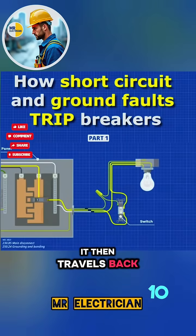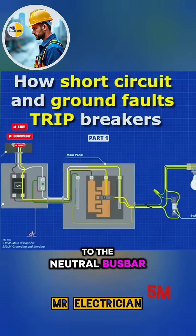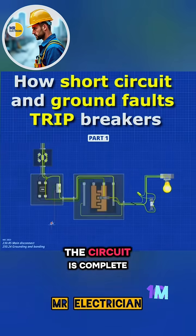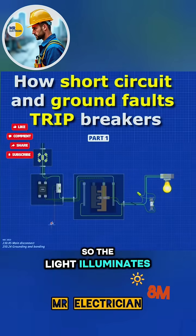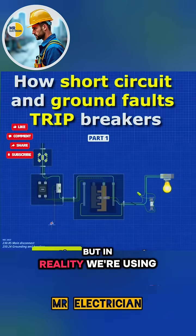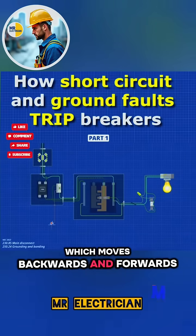It then travels back along the neutral wire to the neutral bus bar, and then back to the main disconnect, then back through the meter and over to the transformer. The circuit is complete, so the light illuminates. Now, I have animated this using DC current as it's easier to visualize, but in reality, we're using alternating current, which moves backwards and forwards like this.